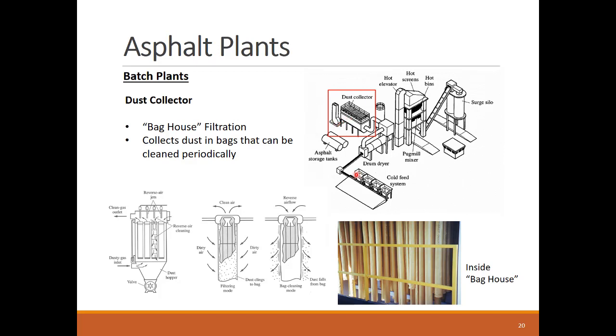In filtration mode, the dust air flows through the filter bag walls, leaving the dust particles hanging on the bag from outside. In the bag cleaning mode, the air flow is reversed to kick the collected dust off the bag.